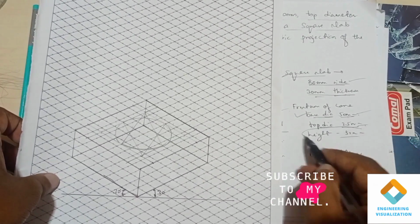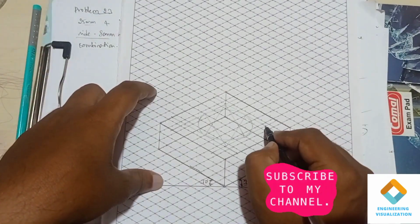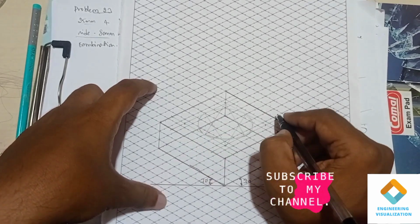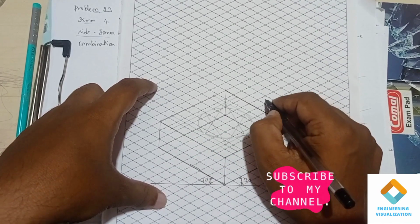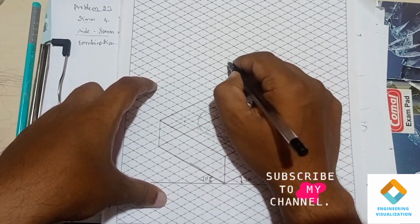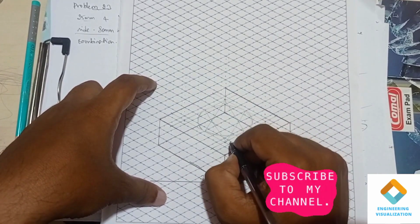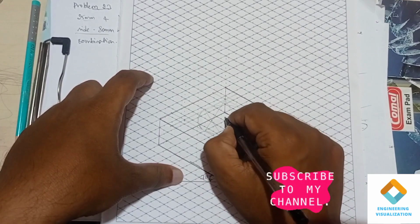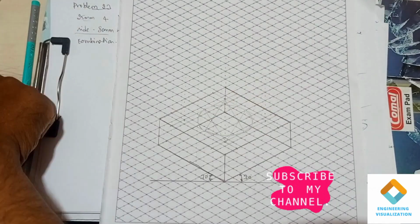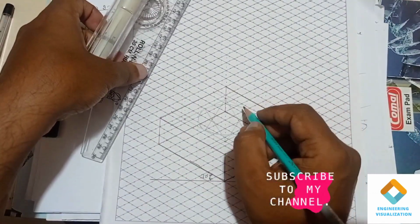Now we have completed the base diameter 50, that is, we have drawn an ellipse here. Now by taking the 50 mm inside box, we have to consider the height. The height is 50, so count the boxes. Here the box count comes from exactly the center of it. So count 5 boxes, and again here we need to construct another box of 50. Now I will be drawing another box here, a box of 50 by 50 at a height of 50 mm.